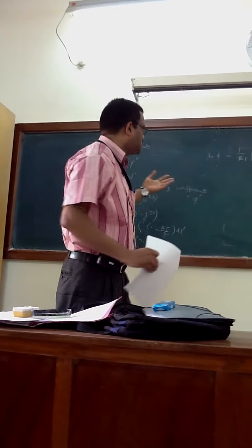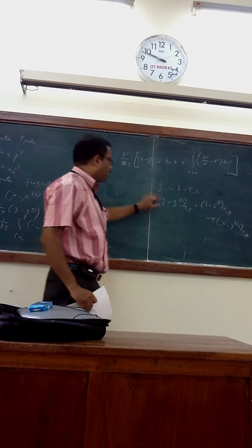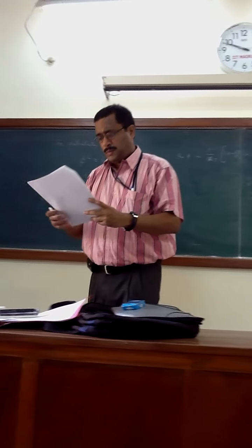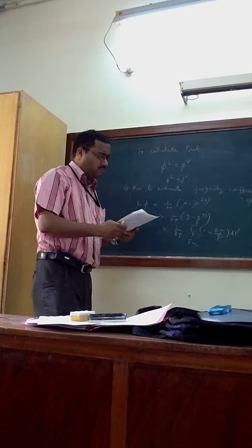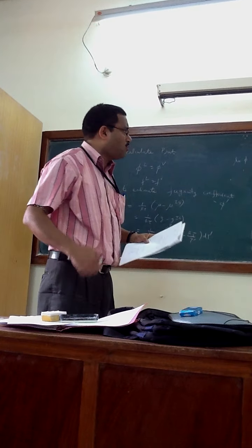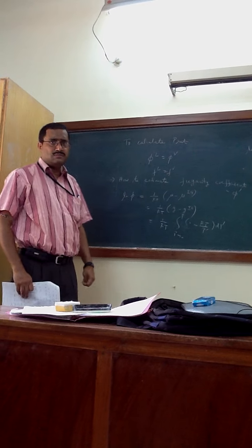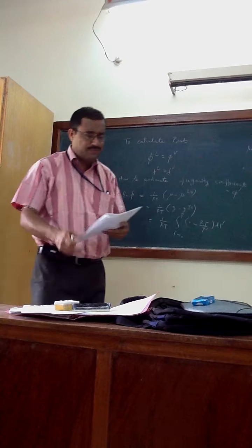So both the ways. This one is from the first principle, and this is for cross-checking, verification. I always go by the first principle. That's always better. So let me talk about how to estimate the fugacity coefficient for liquid and vapor. You have to estimate liquid and vapor, right? Phi L and phi V.